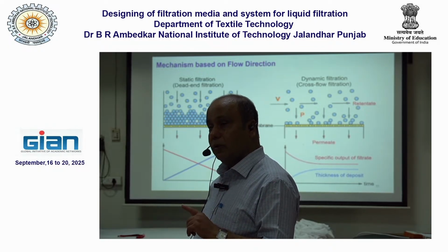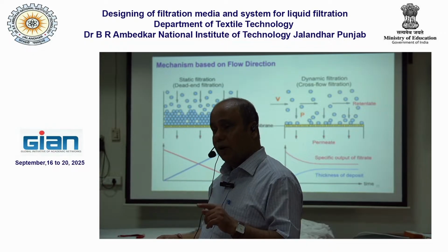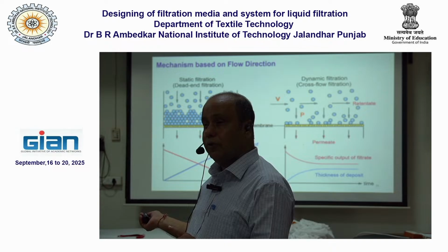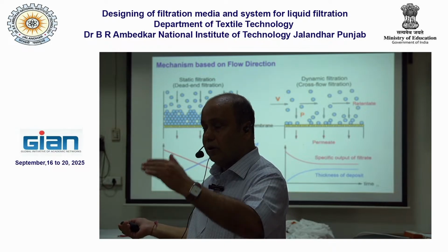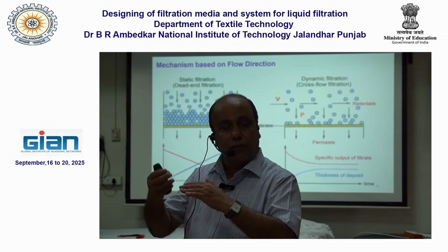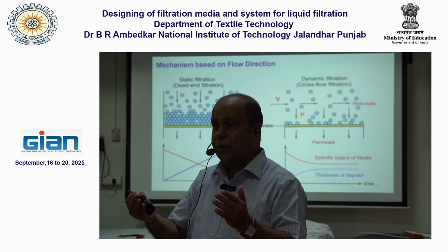Yes, in cross flow, for example, if contaminants are very less, in that case also people can go for cross flow filtration. For example, for separation of bacteria and virus, you can have cross flow filtration, and that will take a lot of time to saturate the media.